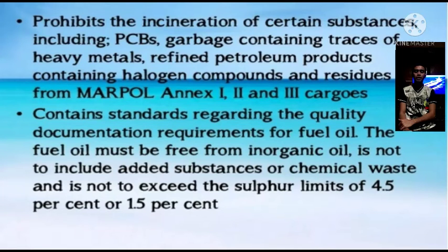Fuel with higher sulfur content than required by Regulation 14 of Annex 6 can be delivered to a ship where the ship uses an equivalent measure such as an exhaust gas cleaning system.